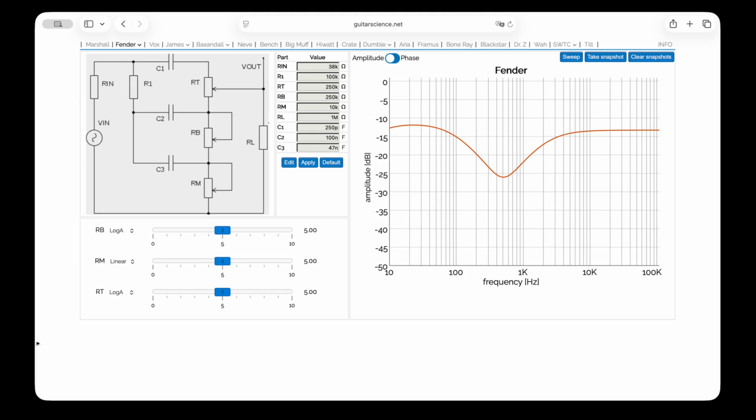And actually I can show you a concrete example of that with tone stacks. So the thing you see here is called Tone Stack Calculator, and it's a popular web app that shows you the frequency response of common tone stack circuits that you can find in guitar amplifiers, for example. Here we are looking at a Fender style tone stack circuit that has treble, mid, and bass.